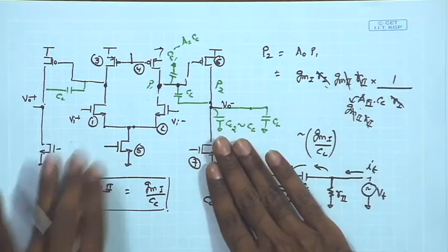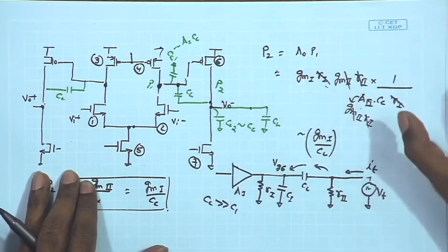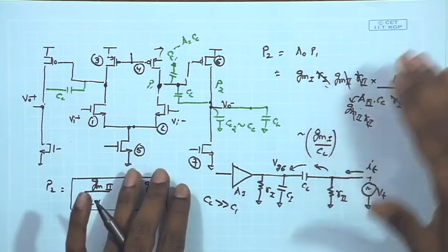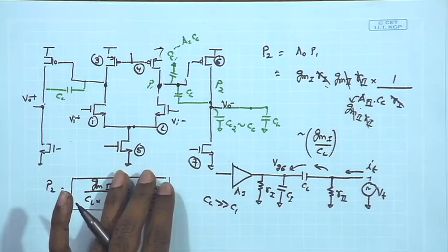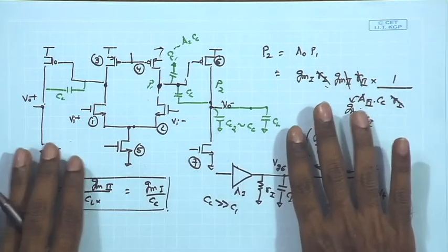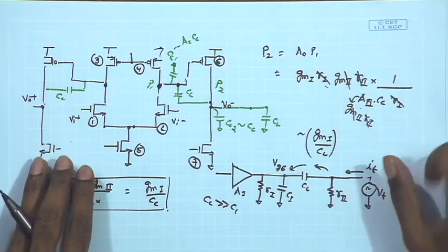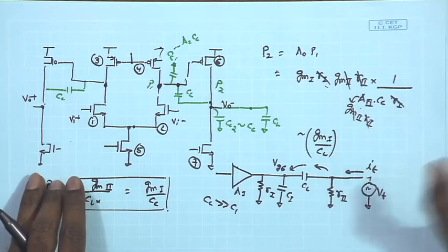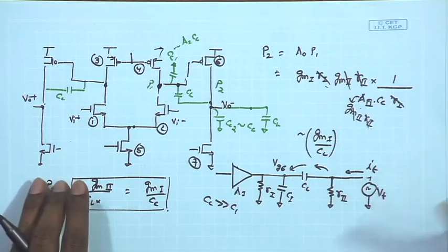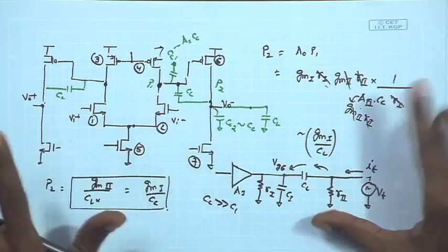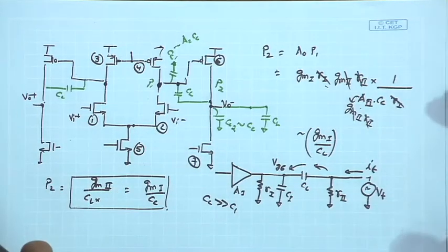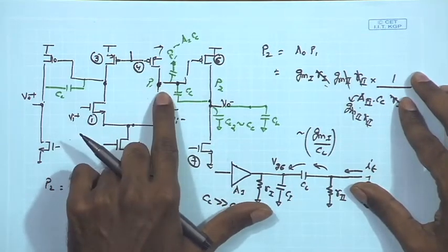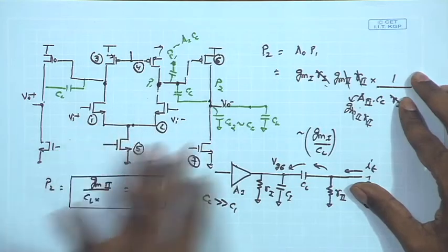If it is a single loop, then we will see that even the error amplifier of the common mode feedback is not going to have a significant pole; the pole of that amplifier is also going to lie at very high frequencies. As we have discussed, in a single loop, just to reduce the overall loop gain, we keep the gain of the error amplifier pretty small by having a direct connected load for both the drains. In that case the dominant poles come only from the first two stages of the amplifier, and the error amplifier does not contribute significantly to the pole. So we need to compensate P1 only, that is the main dominant pole for the differential response as well as the common mode response.